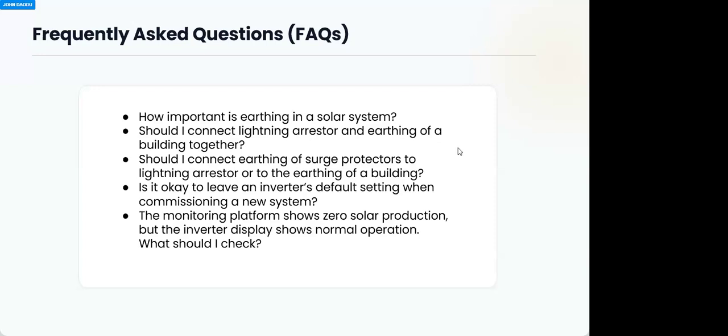If the breaker will trip, or the input breaker is not enough, because when the grid comes, it's the same breaker that will power the inverter for charging and then power the load. Now, the inverter is demanding on current, and you are using maybe 20 amps at the input when it's supposed to be like 100 amps. The breaker will trip. So all these are very important. So I think that answered your question.